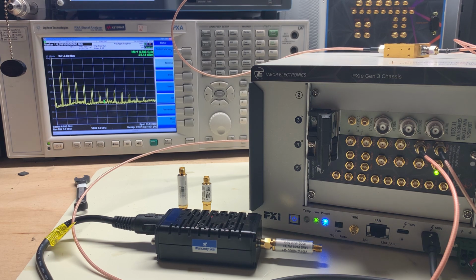From our previous example, you can see that we have the 75 megahertz pulses, and they appear at multiples of the clock frequency. So on the spectrum analyzer to the very left, you can see the fundamental 75 megahertz pulse, and then you can see images of that at 1 gigahertz, 2, 3, 4, 5 gigahertz, and the span of the spectrum analyzer is set to 13 gigahertz. So you can see we're going all the way up to around 12. We can see images all the way up to 12, and that's a good thing and it's a bad thing.